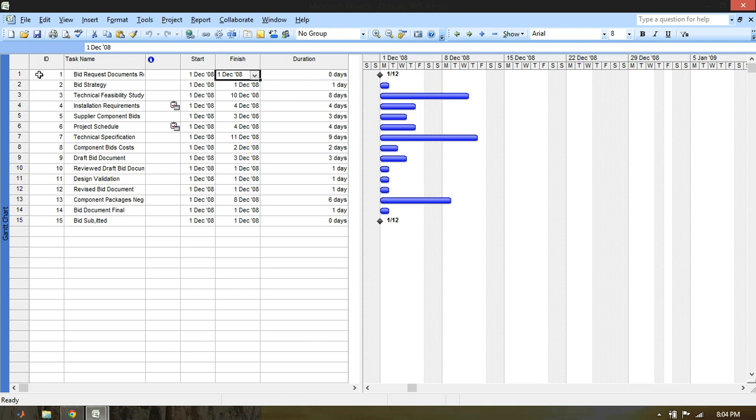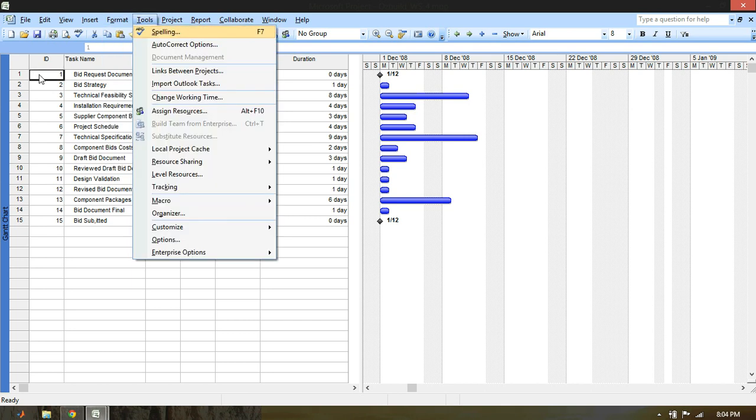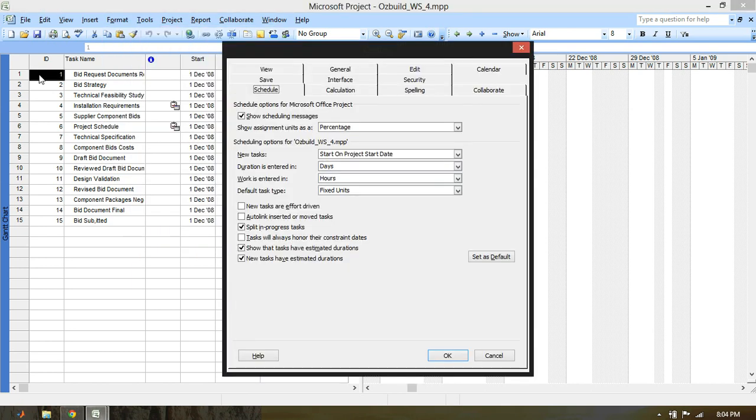Okay, so first of all, it states to go to the View tab in the Tools and Options menu. So go Alt-T, and then O. Make sure when you're using hotkeys that you actually keep your finger on the Alt button. Otherwise, it'll think it's another command, and it'll open up a different menu and stuff. So make sure you keep it down.